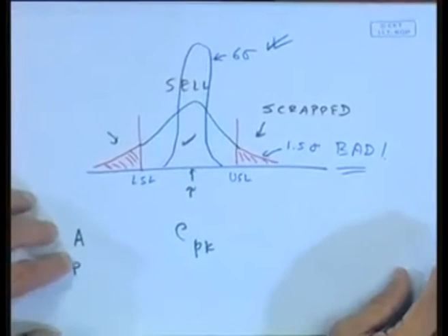And you take a good look at the training level at which people are performing their quality control tasks. Quality control inspectors, are they really trained to use those equipment, those instruments, and so on and so forth? Do they produce good results? What about your overall gauge R&R variability? Is that sufficiently small? When you look at process variability, suppose you are trying to measure, for example, this old picture that I had there.